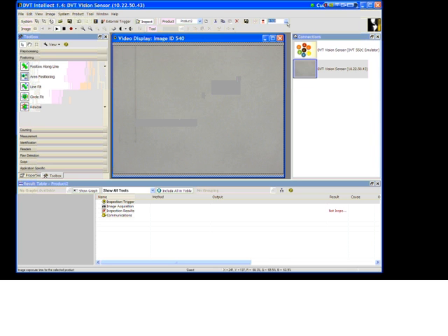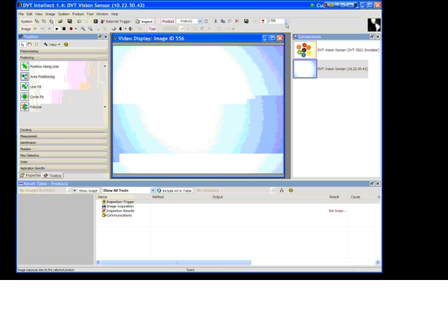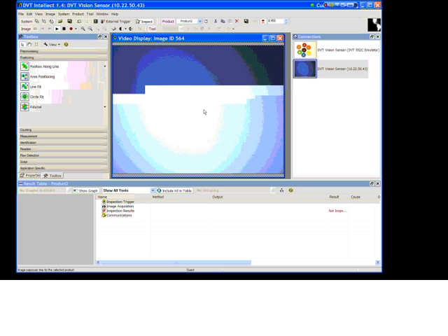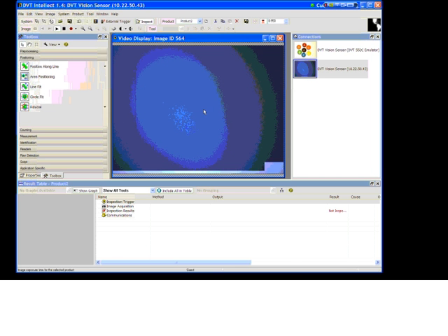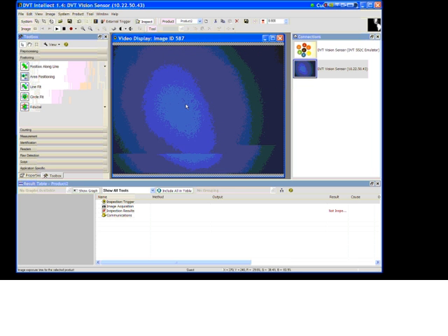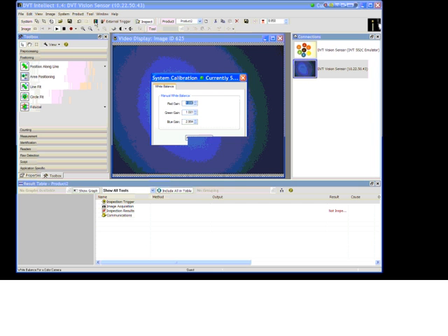If we change the illumination, in this case I'm turning on the white LEDs, the front of the camera, you'd see that because the content of that light source is a little bit different, now our image is very blue, and that's because white LEDs are blue LEDs, modified blue LEDs with a phosphorus coat on top of it. So if we want to use this lighting technique, or change the lighting source, then we need to do a white balance operation, and that is done using this button of the toolbar. If I press that button, I get something like this.